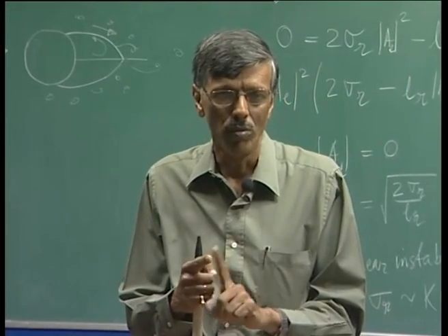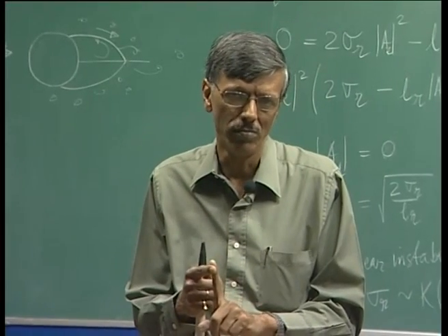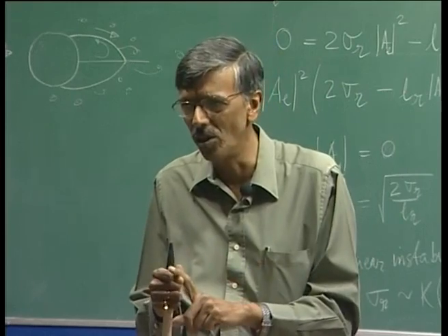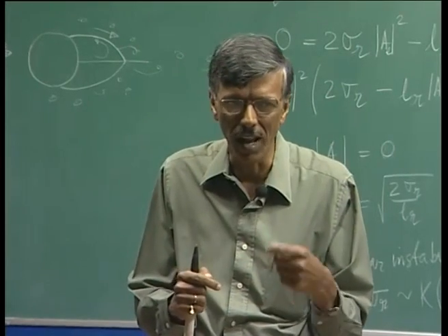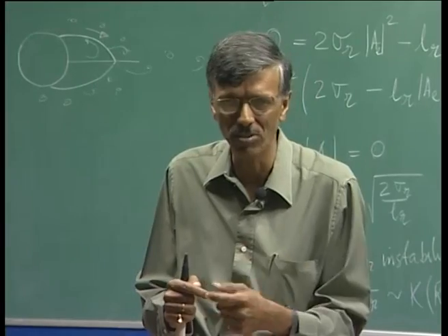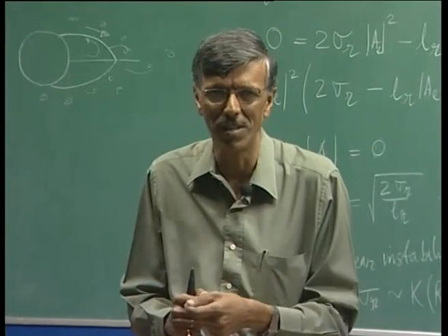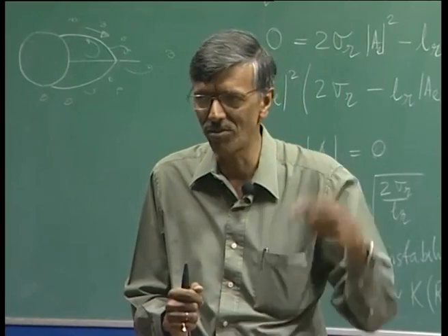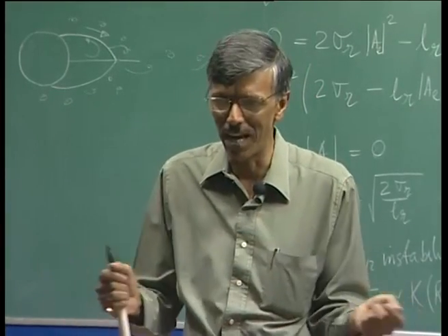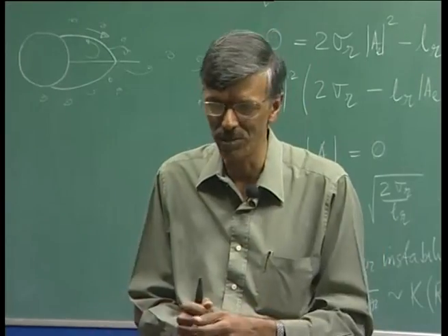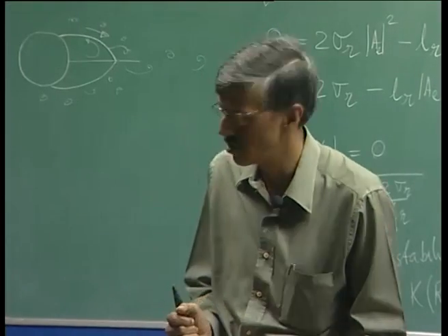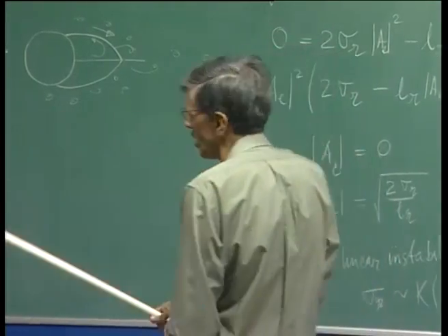The problem is two. One is, of course, the amplitude is too low, so you would not know with reliability what it is that you are studying. And the second thing is that it is much easier to measure the frequency. I will get the oscillation, and once I have the time trace, I can do a Fourier transform and obtain the Strouhal number. So, this is what we are talking about.